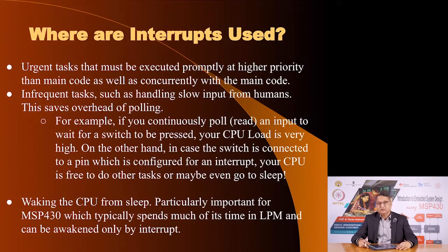Infrequent tasks which happen once in a while, you would like to deal with using an interrupt, and as I mentioned, human inputs are very slow. They may be infrequent compared to the rate at which a microcontroller can execute a program. Human interaction is much less frequent, and so you could handle the external events generated by human inputs through interrupts.